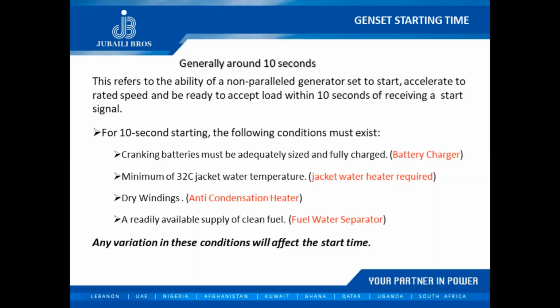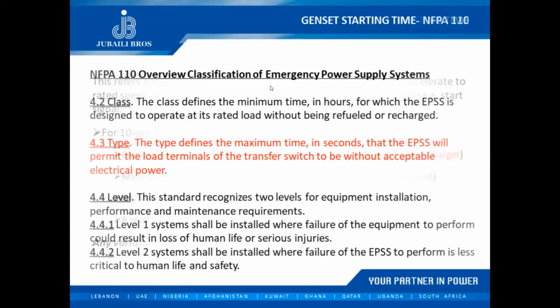So where did this 10 seconds come from? It came from NFPA 110 type 10. And it's not really 10 seconds for the genset to reach rated frequency and voltage.